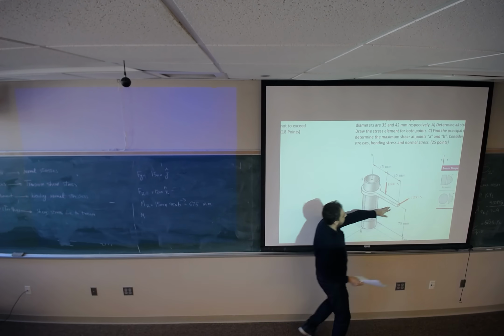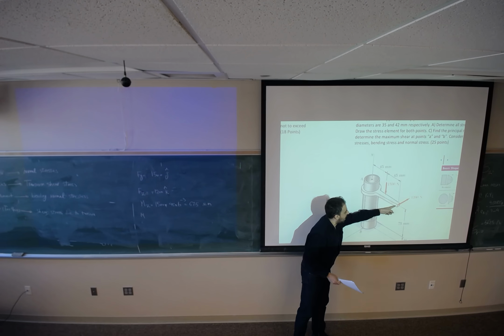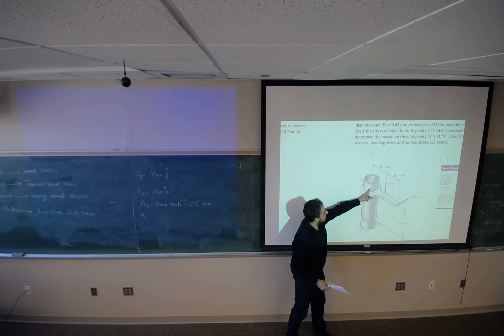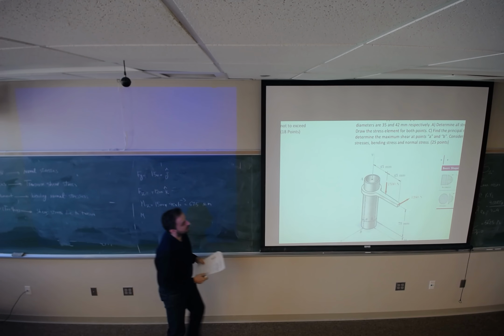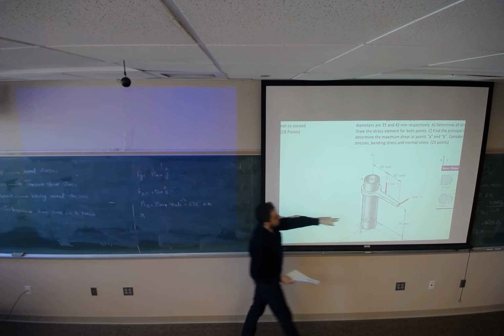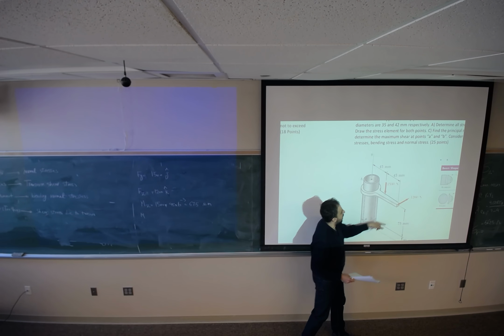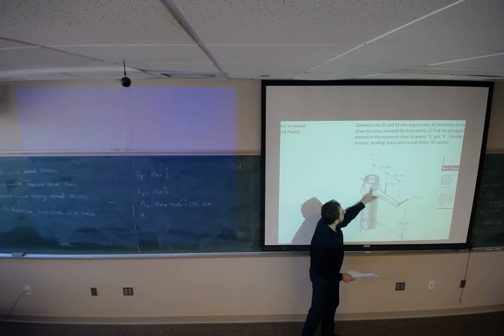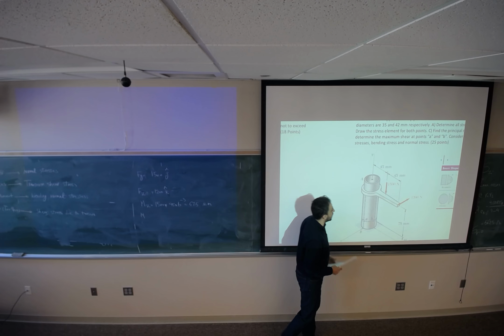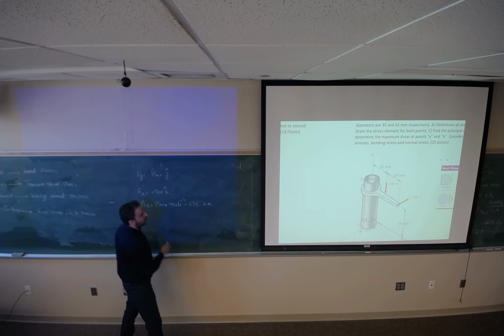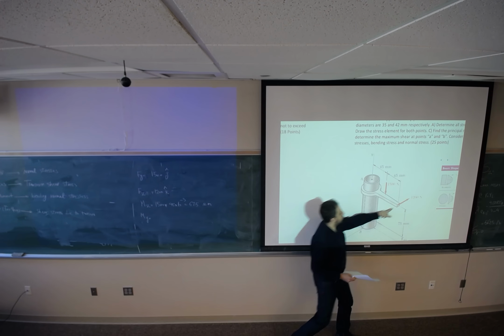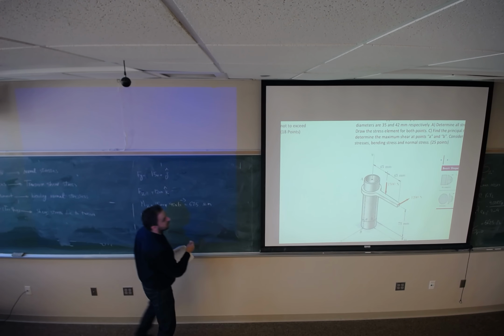Now, this force has a distance in two directions from this section. One is this distance in this direction, and the other distance would be in y direction. This force times this distance: force is in z direction, distance is in x direction, so it's making a moment about the y axis. So M_y would be force times this distance times 90.